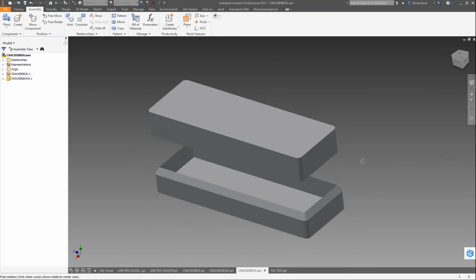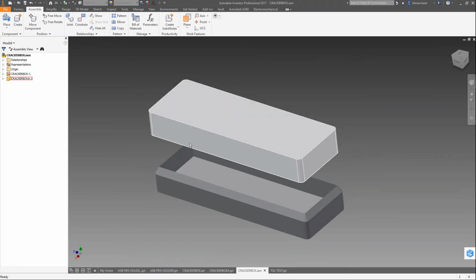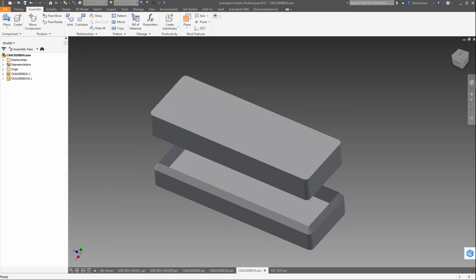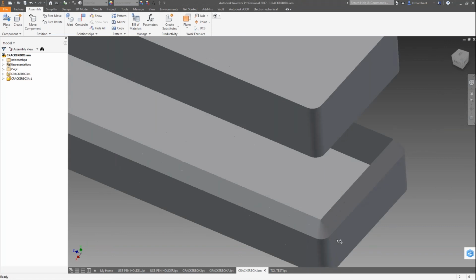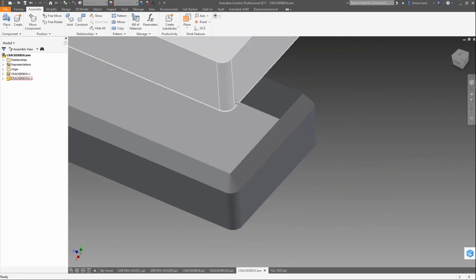Again, if I was going to machine that, the other thing that I would do is I would change this. That would end up being a very, very sharp edge that I would not want on a machine. I'd go to a corner lap, similar to a snap together box, that would allow the same type of side-to-side resistance, but much smaller due to the strength of the metal versus the strength of the polymer plastic or whichever filament I was using in the printer at that time.